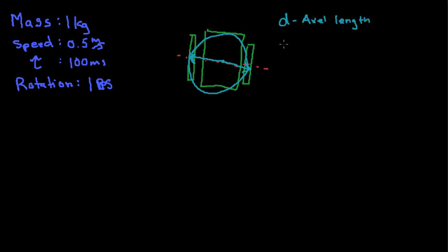To get the rotation speed, we just have to find the circumference of the circle circumscribed by this spinning behavior, which is pi d. This describes the distance per rotation. And of course, we know the linear travel velocity of each wheel, described by v, which gives us the distance per second.